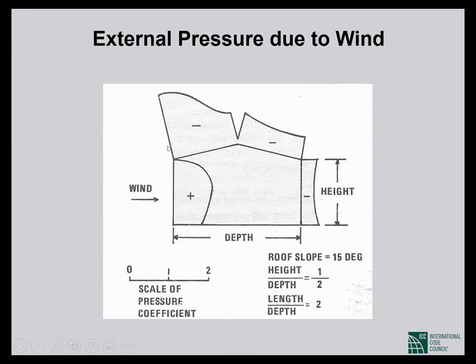This is a very basic problem in wind design. Because of that very high suction, the windward roof may be sucked up. Okay, wind may suck it up, and when that happens, this wall loses lateral support, and then it doesn't take much for the wall to come down, and that's the end of the building.